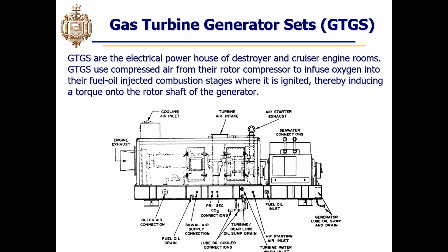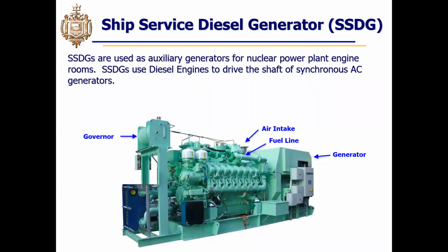The prime mover, of course, spins a generator. These units also have governors, which control the amount of fuel intake and the timing of the spark ignition, which controls the speed of the generator. And of course, the generator is going to be making a constant 60 hertz output. So the idea is to keep the speed constant and to vary the amount of fuel admission in response to the load on the generator.